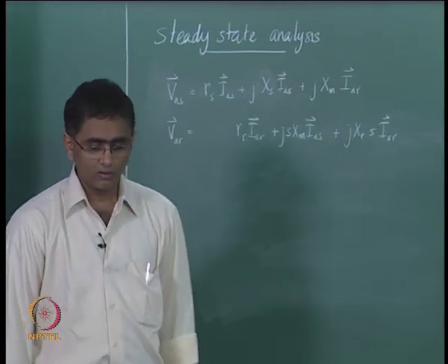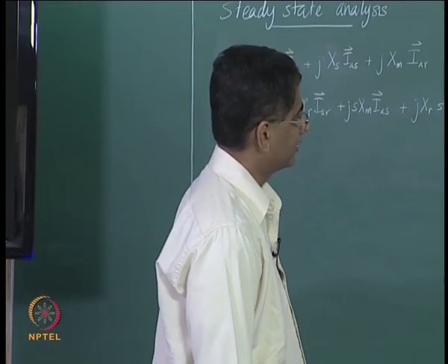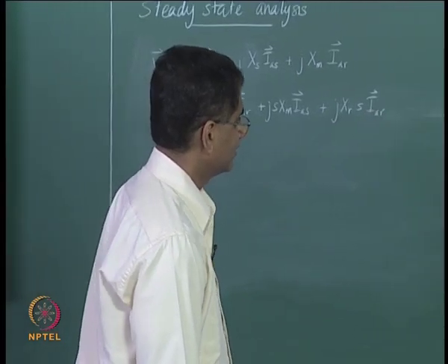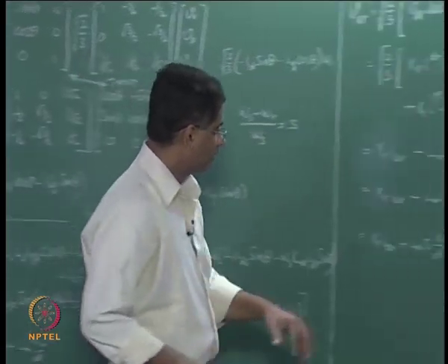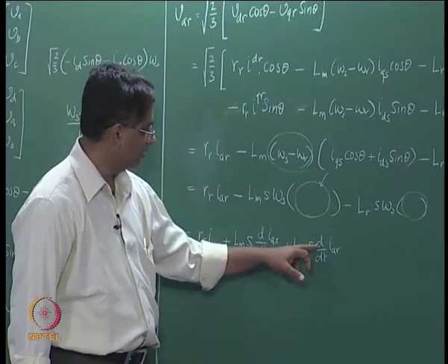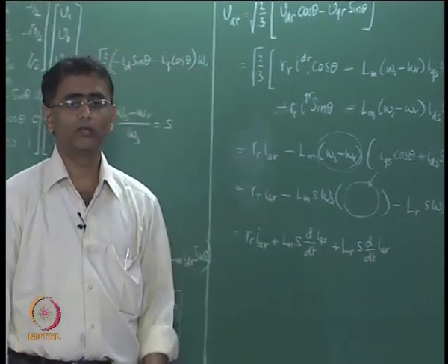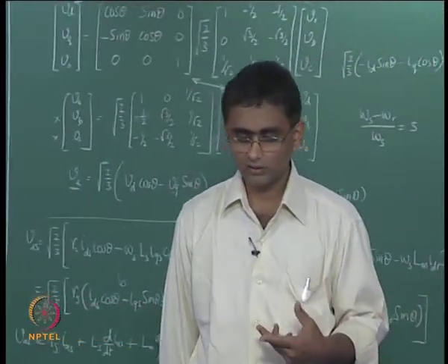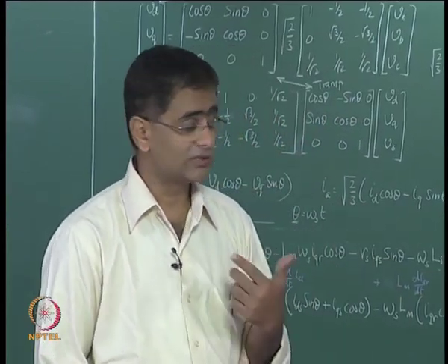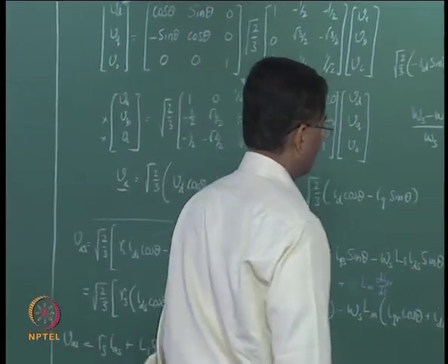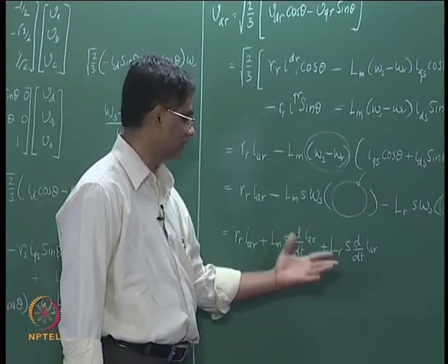Now you may have a doubt that comes up at this instant. Now we are looking at doing a differentiation of IAR, and the rotor current in reality is not at the frequency of the supply, but it is at the frequency of slip. So one may ask why slip frequency is not coming.